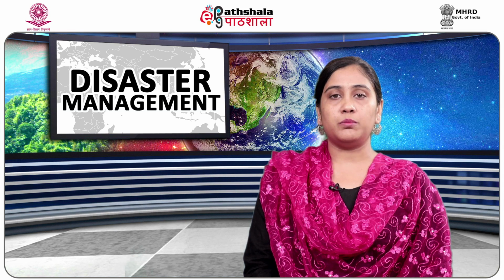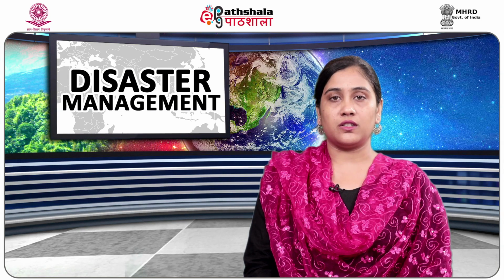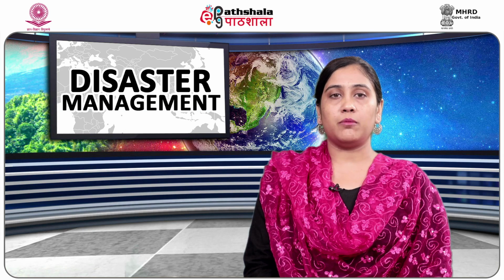IS 1893-2002 is the Indian standard pertaining to the zonation of seismic hazard. It has been modified on at least 5 occasions, with the major ones post Latur 1993 and Bhuj 2001 earthquakes. Zonation at a national level is thus not sufficient to assess and prepare for seismic hazard. Tremors were felt in Delhi in correspondence with earthquakes as far away as Nepal or Afghanistan. Thus, the changes observed in intensity of earthquakes due to changes in geological and geomorphological configuration within the zones led to the requirement of microzonation for seismic hazard.